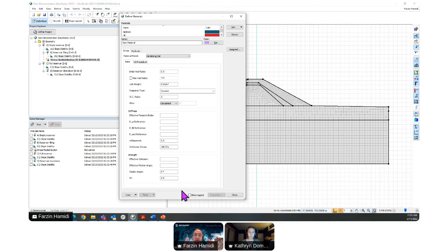The thing I want to highlight is that it's better to start with a simple analysis, and once you are 100% sure about the output results and that your input is correct, based on the validation test you have, then go and put the same input into your complex geometry and run the analysis for that one. So start with simple and gradually make it complex.